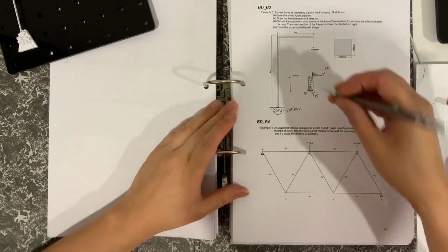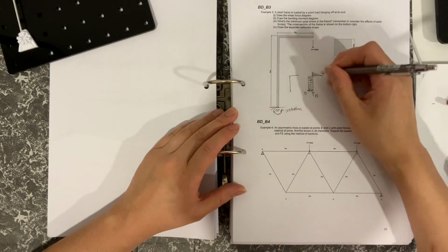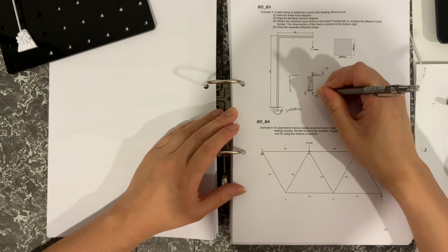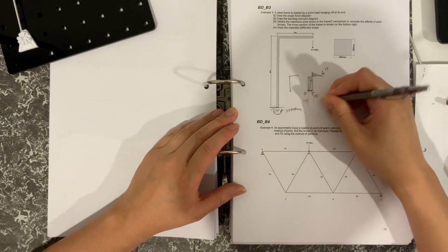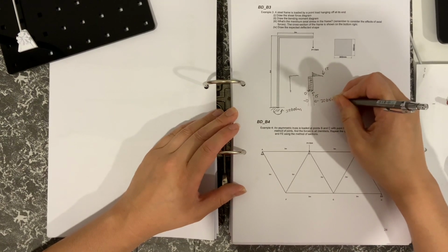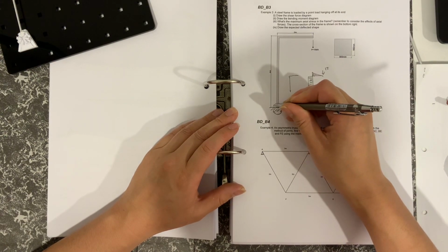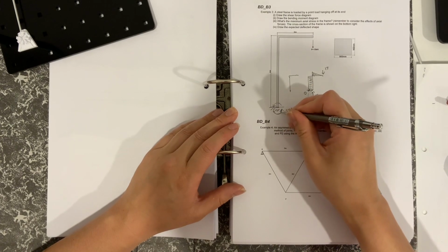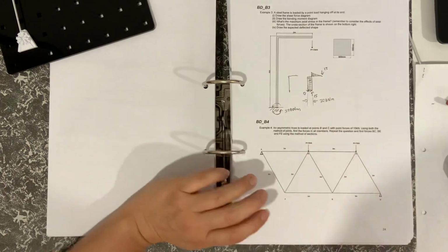Shear force diagram. Well, the magnitude of the bending moment diagram is of course going to be 30 kilonewton meters, and you could turn that round there and put the arrow on, so the whole thing is going round, and the bending moment diagram is plotted on the same side as that arrow.